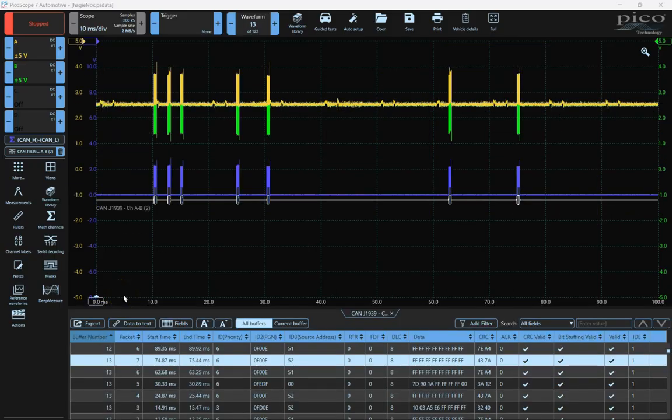So one other thing I should probably mention, I indicated that the complaint on this machine was I was setting the .09, the timeout codes for both of the NOx sensors, so source address 51 and source address 52 in hex. So I didn't set the timeout fault for the DEF header though, because it's on the same CAN bus. So this becomes one of those things that makes it very confusing. This would be a problem like an intermittent short to ground. You would expect that would cause problems with the DEF header communication as well, which it would. The difference is the frequency that the messages are transmitted or expected.